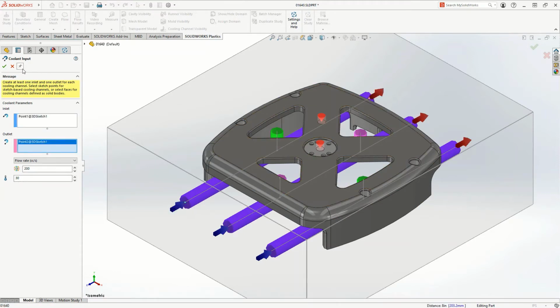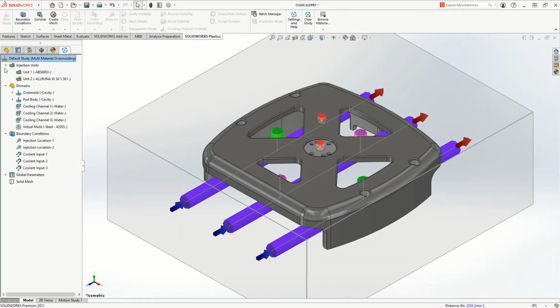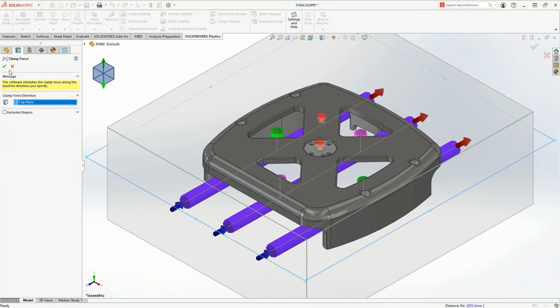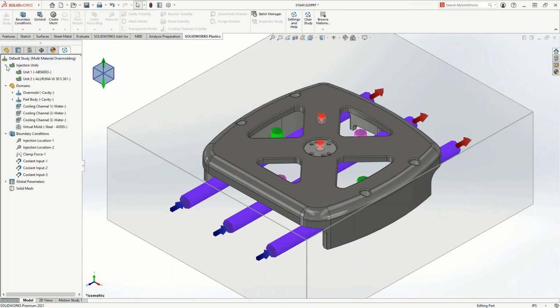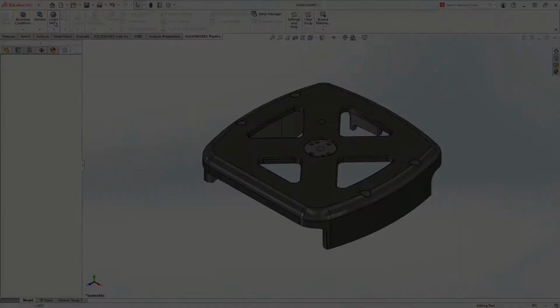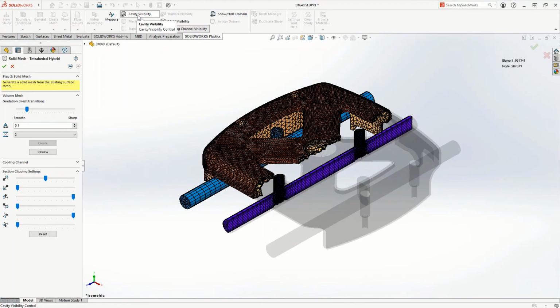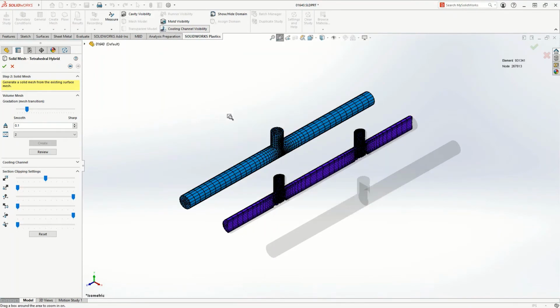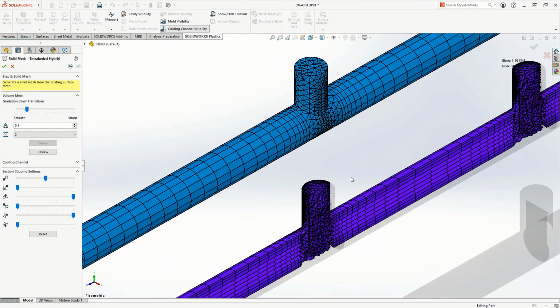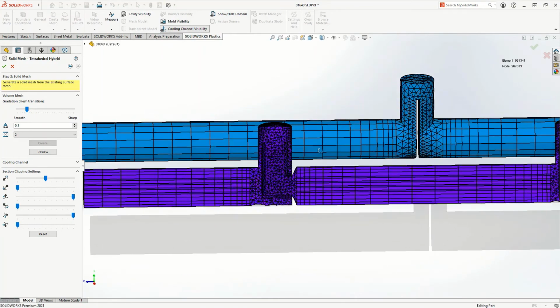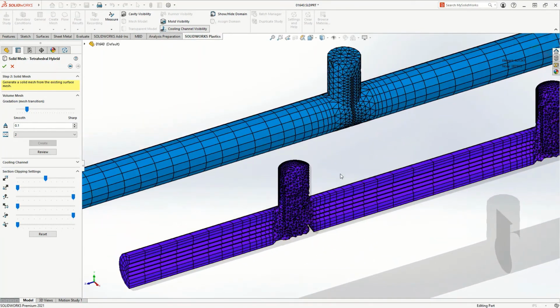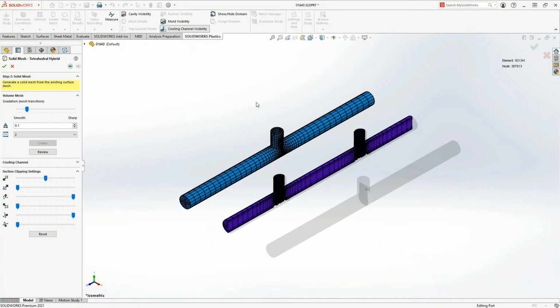This includes other design elements such as the cooling channel inputs and outputs, as well as things like the clamp force direction. The entire plastics analysis has been defined geometrically and virtually. This makes the file on disk smaller, portable, and more adaptive to changes. Eventually, when you do mesh the model in preparation for the final simulation, you will immediately see the benefit of those improved baffles and bubblers defined earlier.